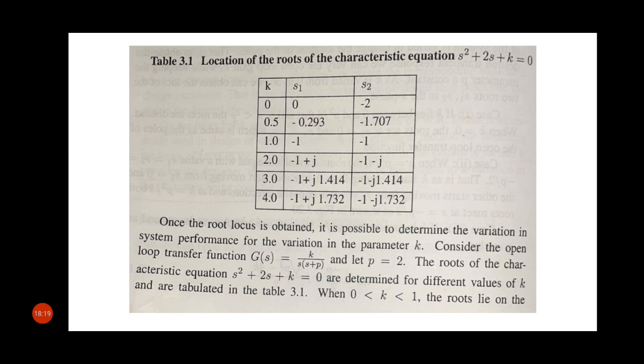When k is between 0 to 1, the roots lie on the negative real axis, which corresponds to an overdamped response.